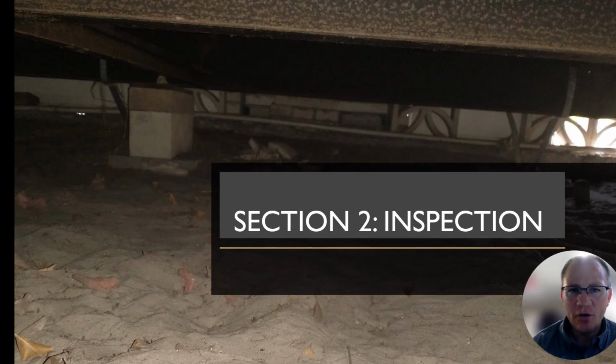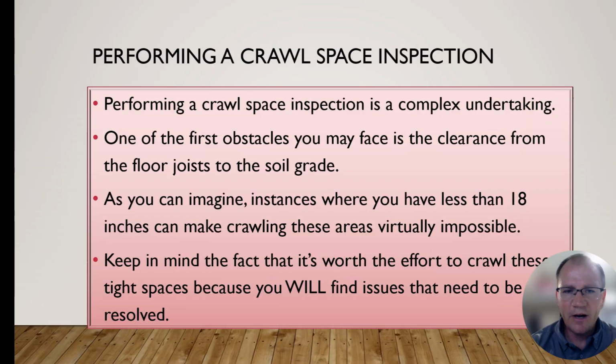In section 2, we're going to talk about inspections. Performing a crawl space inspection. Remember, performing a crawl space inspection is a complex undertaking. One of the first obstacles you may face is the clearance from the floor joist to the soil grade. As you can imagine, instances where you have less than 18 inches can make crawling these areas virtually impossible.